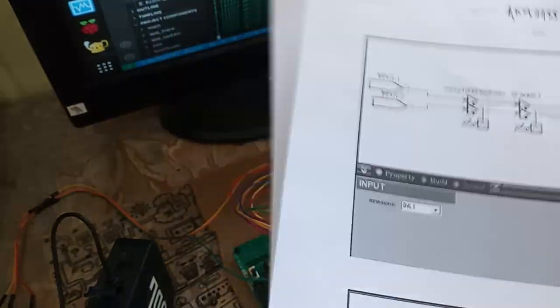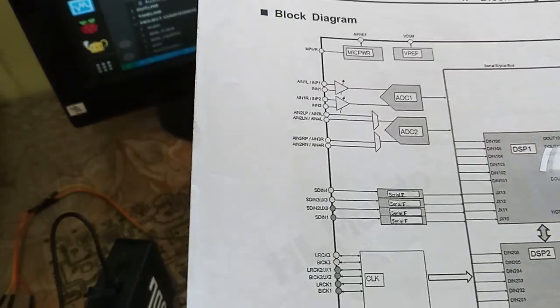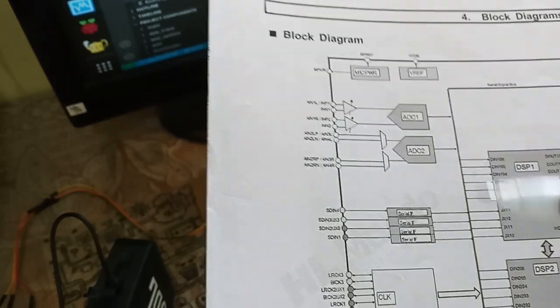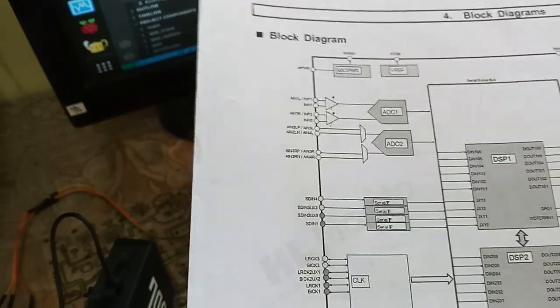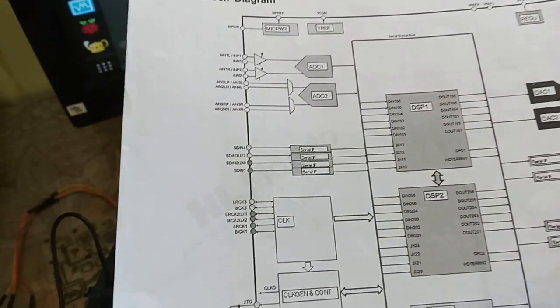This is the program we configured and generated, and we downloaded it into the DSP memory of this AK7735. It is run at the time of power up of the DSP of this audio codec, and that is coming to the SRC1.